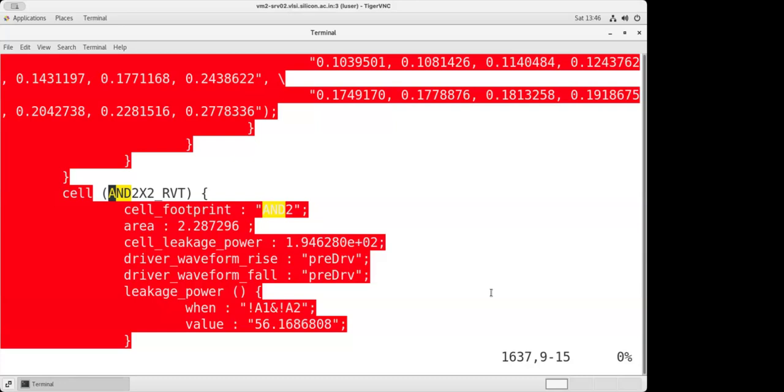So at each and every stage in physical design, there is some linking. You will see that particular message. If linking fails, you will not be able to do anything. So you have to link it. The message will say, I'm linking the design with this particular library. And if the linking is successful, then you can do the rest.